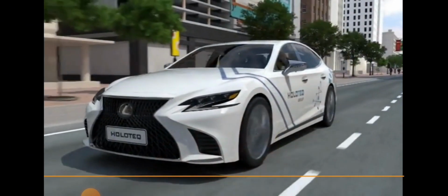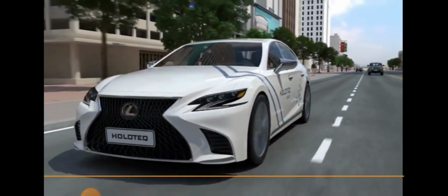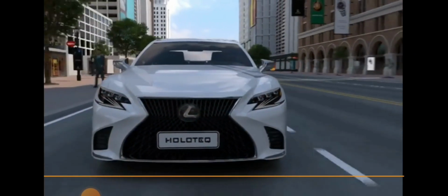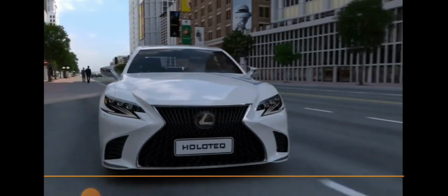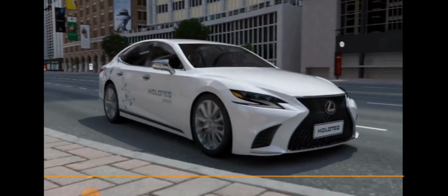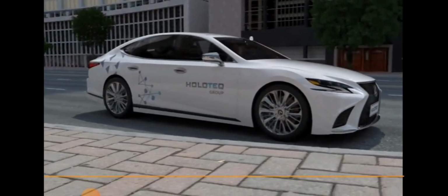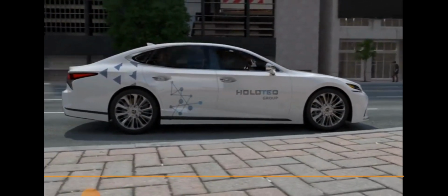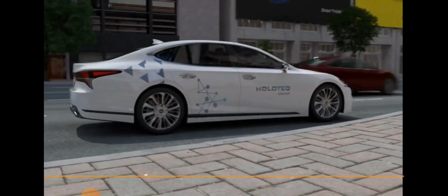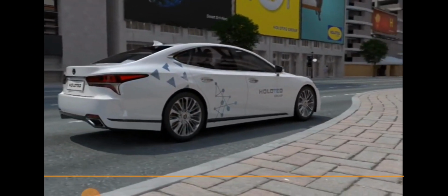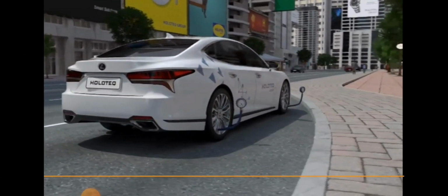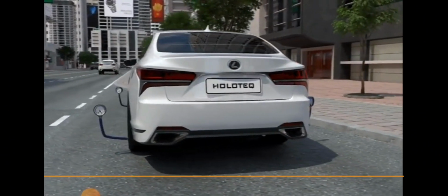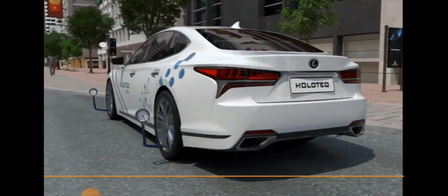Tires. The tire holds vehicle weight, transmits the motion from the vehicle to the road, and absorbs part of the shocks, and through which vehicle can be stopped or steered. Therefore, tire is the most important part of the vehicle, and any fault thereof adversely affects safety of vehicle motion on the road. So, tires must be checked continuously and make sure that there are no damages in the tire, and to measure air pressure, where the decrease of tire air pressure leads to its damage and loss of control on the vehicle, and the increase of pressure as well.